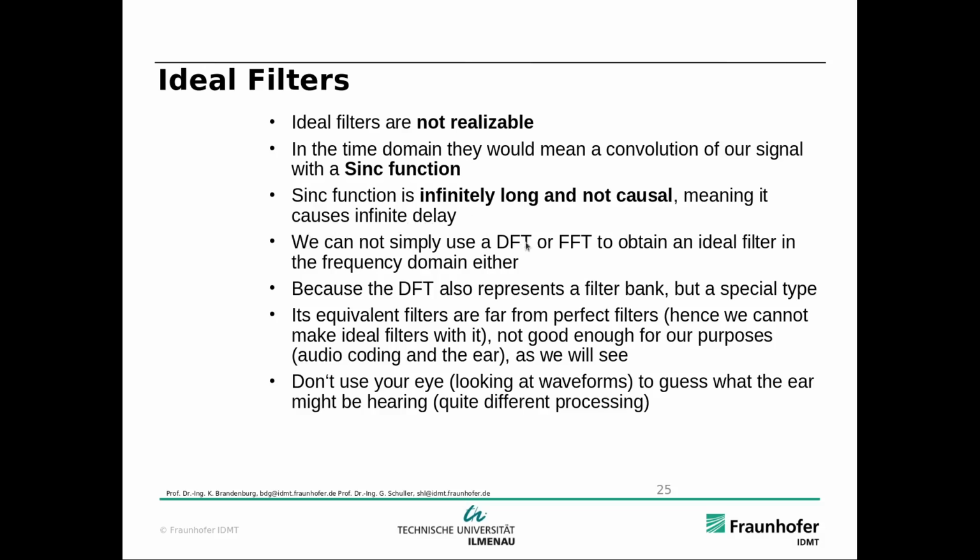And we also cannot simply use a DFT or FFT to obtain an ideal filter in the frequency domain either, because the DFT also represents a filter bank, but a special type. Its equivalent filters are far from perfect filters, hence we cannot make ideal filters with it, which is not good enough for our purposes for audio coding in the ear, as we will see.